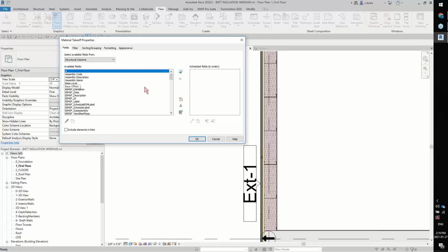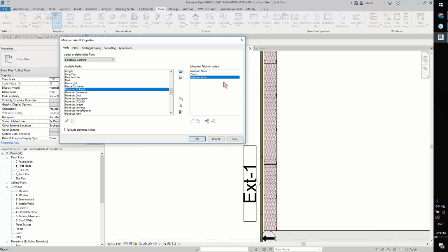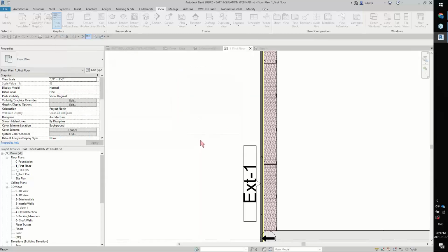And I'm going to say OK. Perfect. Now for the fields that we're going to enter, I'm going to enter 3 fields, but do keep in mind if you needed to bring in other fields that are here, you can always do that. But for today's webinar, I'm going to just call out the material name because that's what we actually want to create a schedule for. So let me come here to material name. Then I'm just going to come in here and bring in the count right here. And finally, I'm going to bring in the material area. So you know how much you need to order. So material area right over here. And I'm going to bring that in. So for now, all I'm going to do is this, and I'm going to hit OK so we can see that schedule get populated.